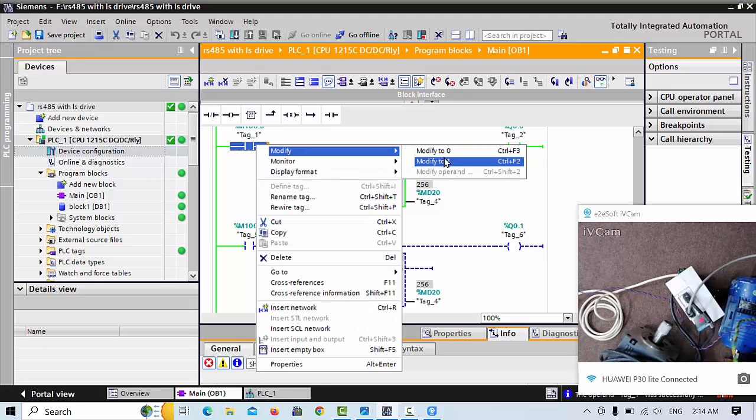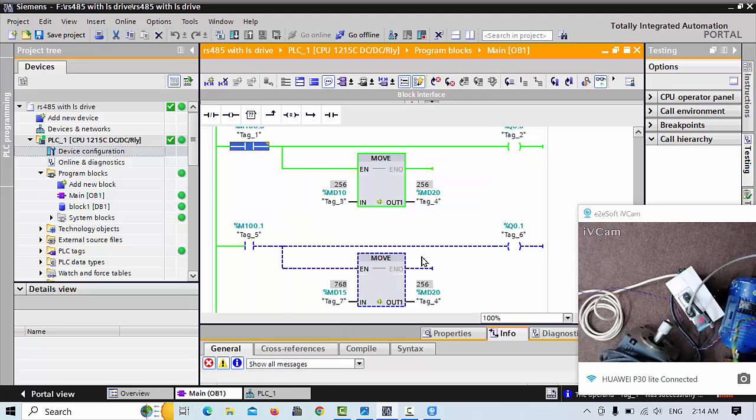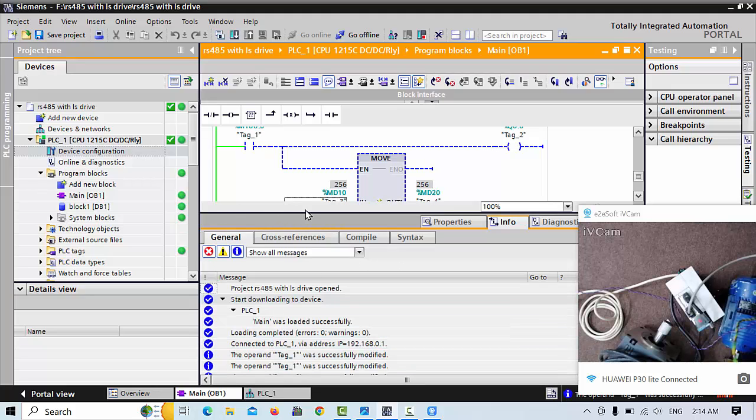I hope you understand about that servo control, how you can make it with analog 0 to 10 volt, but this system is running with 0 to 20 milliamperes, because this PLC does not have an analog output in voltage. But this is no issue, you can use milliamperes also. This will be running.